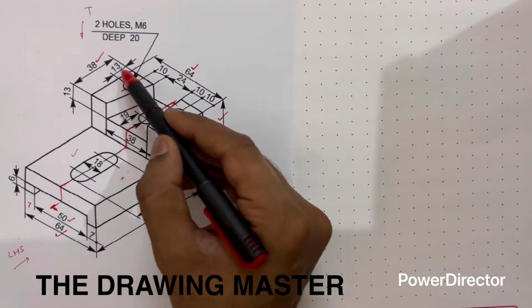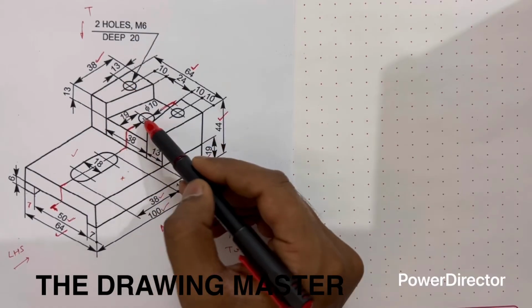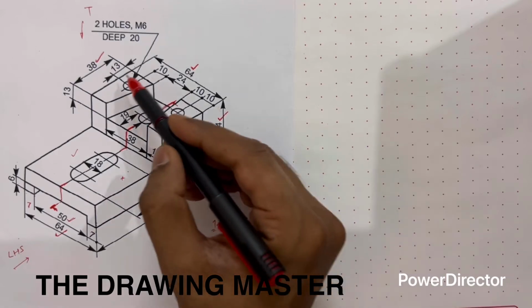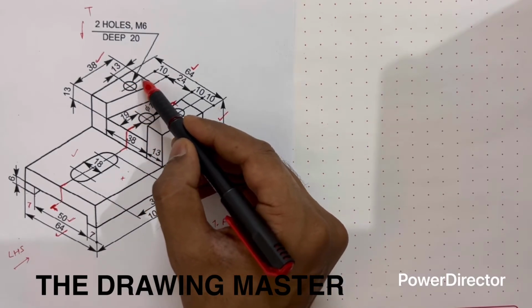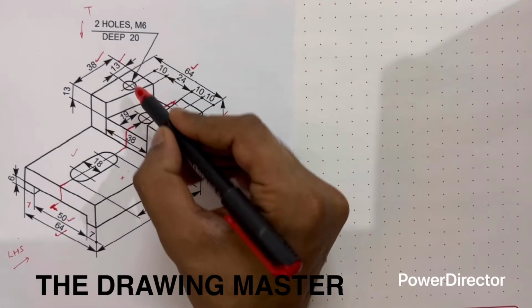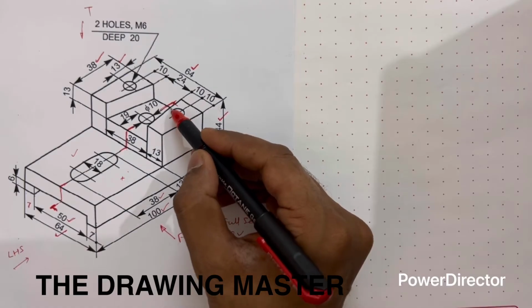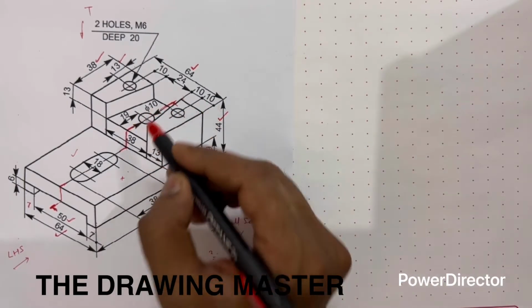So at half of 38, that is 19 mm, there is a circular hole. This circular hole is not at the center. Here the margin is given as 13, this side, and from here it is 10. These are the coordinates. Dia is 10.